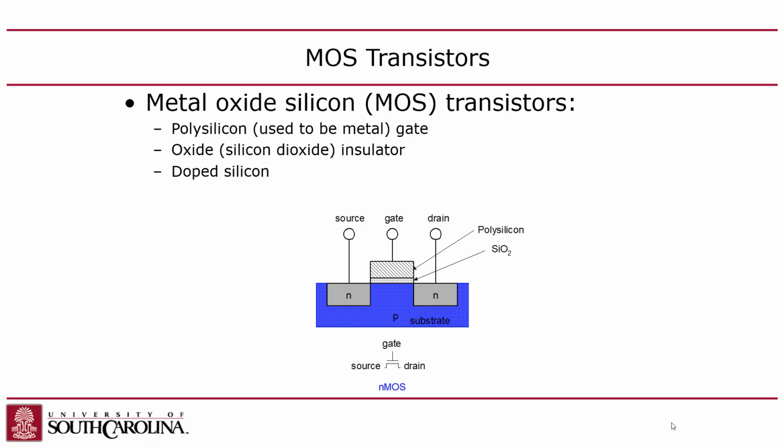And the way this happens is this silicon is doped P, right? So you take boron and you blast the boron in there. First you grow the silicon, then you blast it with boron. But then you take your arsenic and you blast arsenic into these two islands. If you already have P-type silicon, but you start doping it as N-type, it'll reverse the doping.